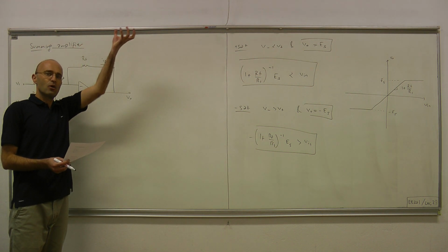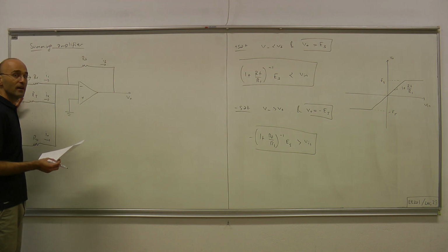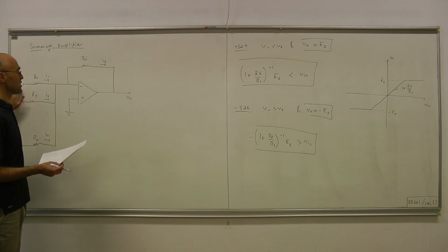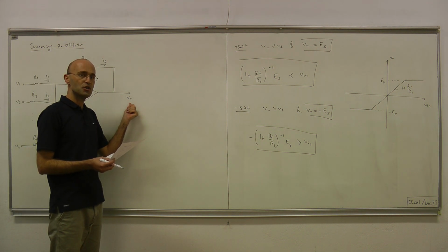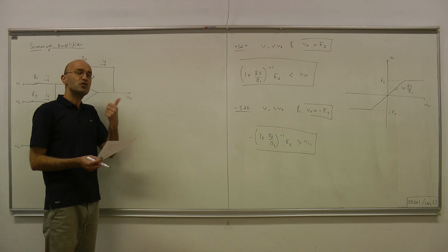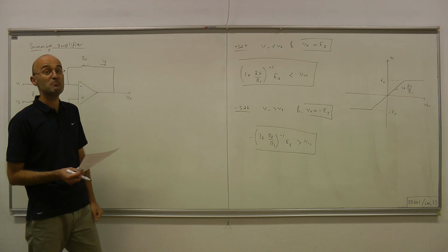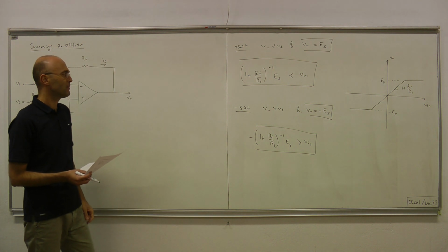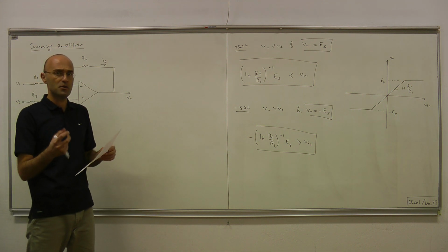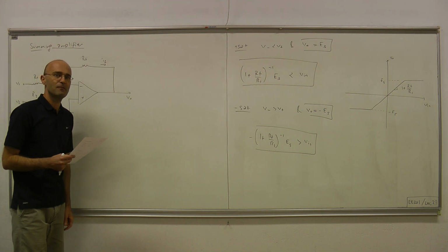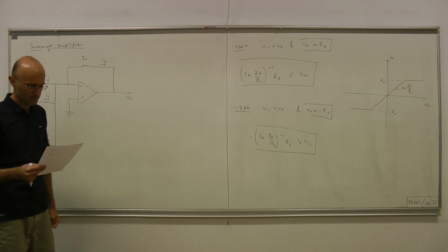The sensors collect temperatures, the physical data, convert them to electrical data, namely voltages, and then you collect those voltages and obtain an average voltage, which carries the average temperature information. And then you send this to, let's say, your decision-making circuitry, so that you either pump heat to the conference room or extract some heat from it, depending on your ideal temperature.